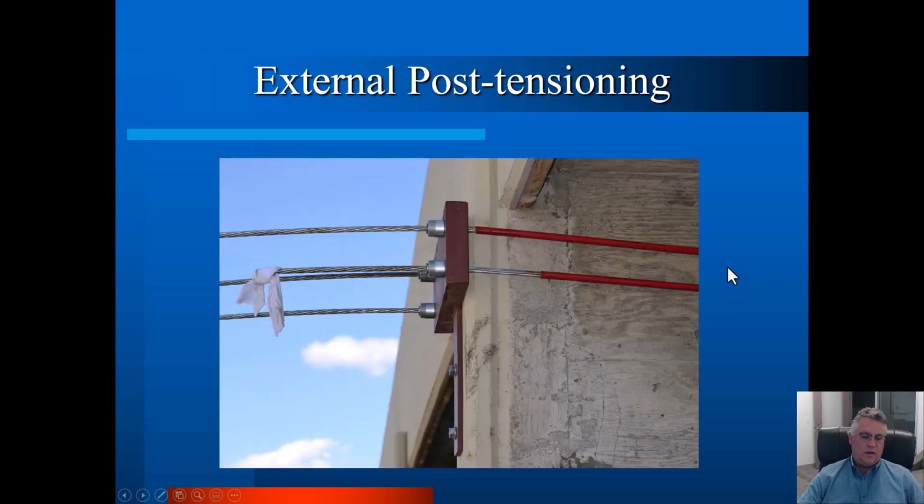You have to get creative when you anchor these external post-tensioning members. You still have a lot of force coming in, and you don't want it to slide down the column, so you need nice bearing plates. These are galvanized tendons, by the way. That's why they're allowed to be somewhat exposed.